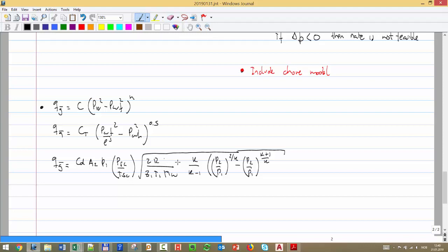And you have one more equation in our case, which is QG equals C flow line times P DC, right? So here it is not P2 or P1, but basically DC over wellhead, and this is wellhead over DC. And finally we have this equation, P separator to the 0.5, right? These are all the equations that I have to solve: the IPR, flow in the formation, flow in the tubing, flow through the choke, and flow through the flow line.